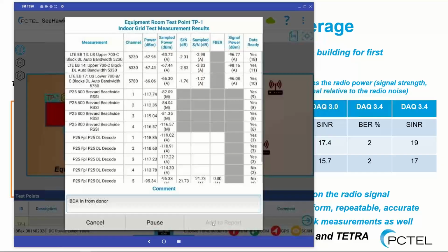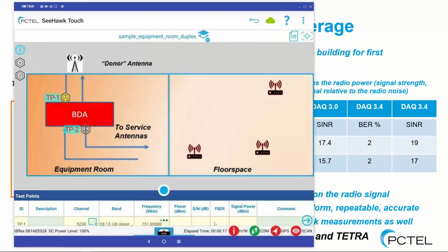Right, that's what I was wondering about. So is there some notion of attenuator or auto attenuation or limit with this equipment? Yes, and I'm going to give you my personal recommendation. If you ask our engineering team, they say you can go 0 or even a little bit higher than 0. I do not like going that high because if you look at the dynamic range of the scanner, the sweet spot is from negative 25 to negative 120. What I mean by that is the accuracy of those measurements. So I try to keep it below negative 25 on the input. And attenuators are a lot cheaper than having to replace an RF board in a scanner.